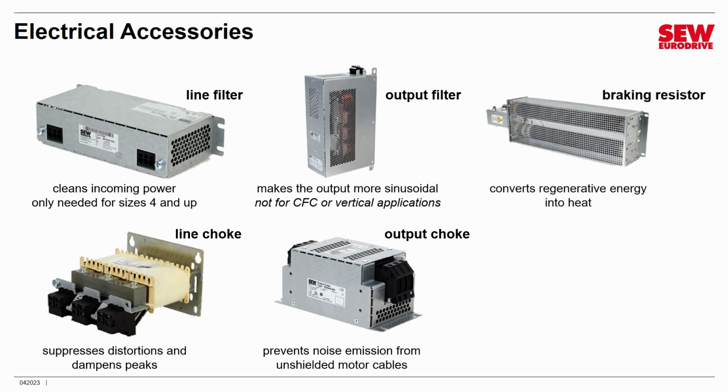We sell brake resistors. Remember I mentioned regenerative energy, how in some cases you recapture that and reuse it. In many applications, you don't need to do that. You just need to deal with it. And a braking resistor is a less expensive, simple way of dealing with it. It takes regenerative energy when the motor becomes a generator. It turns it into heat in the braking resistor, and it just floats away into the environment. So we sell braking resistors of varying sizes for different VFDs.